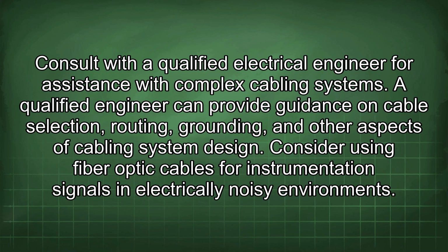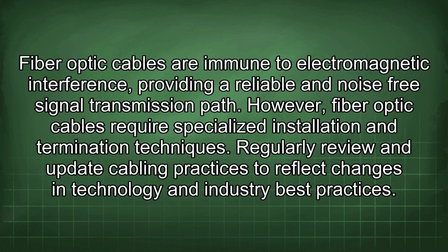Consider using fiber optic cables for instrumentation signals in electrically noisy environments. Fiber optic cables are immune to electromagnetic interference, providing a reliable and noise-free signal transmission path. However, fiber optic cables require specialized installation and termination techniques.